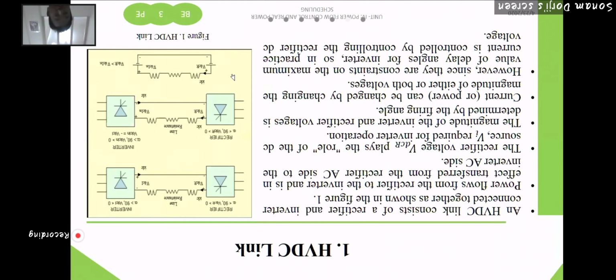You have learned the classification of short, medium and long transmission lines. The HVDC link is advantageous and cheap if the distance is large, whereas for a short distance the cost involved in procuring and using these power electronics devices will be much more than the profit you will get. That's why in short distance transmission lines you will not see this, but this is also another way in which we can control the power flow.